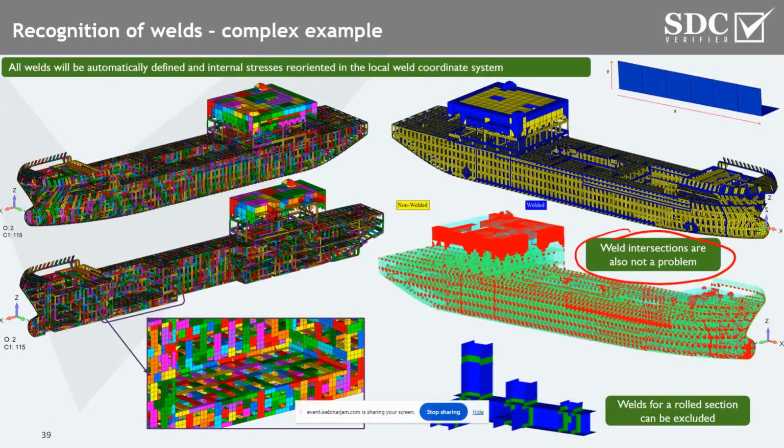Idea is that all your finite element results, so the stresses, will be automatically converted in weld direction and then further used, for example, for fatigue checks. And yeah, similar logic is, of course, for checking the weld capacity. You would say, okay, nice, this is all works for plate model, also for beams, by the way, but what about solids?